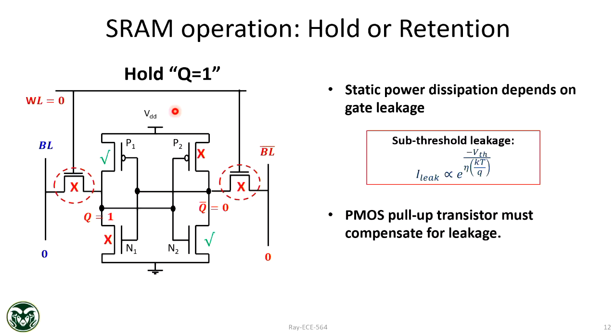Because everything is power driven right now. Because post-Dennard scaling, power dissipation is the main design criterion. So you will operate the SRAM at a low voltage, which is called data retention voltage. Every SRAM will come with this voltage. Do you want a high data retention voltage or a low data retention voltage for a good cell? Low, because you want to retain data at say 0.1 volt or 0.2 volt, but maybe your technology will not allow it. And what decides that?